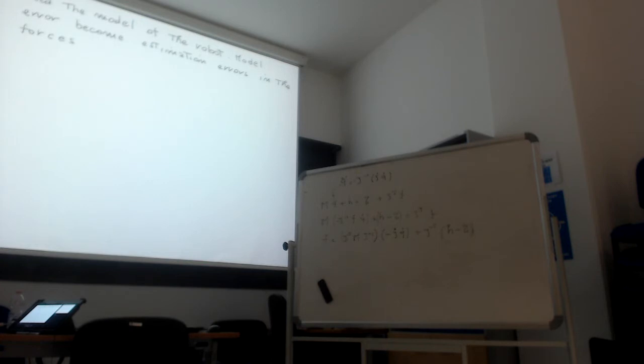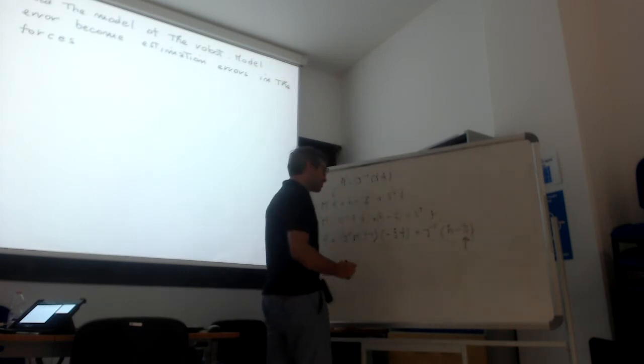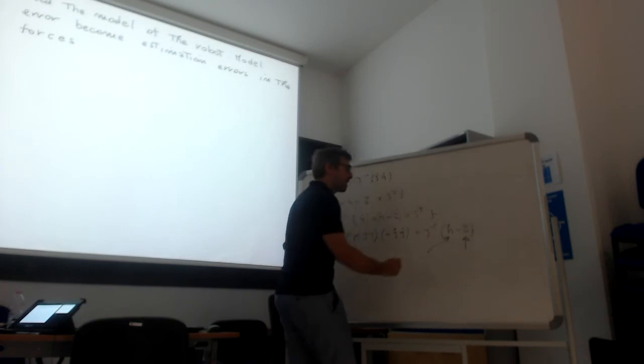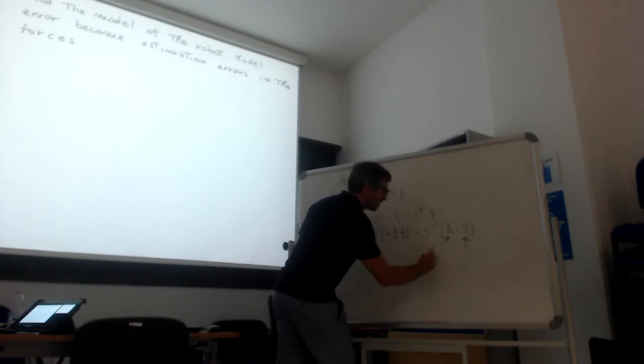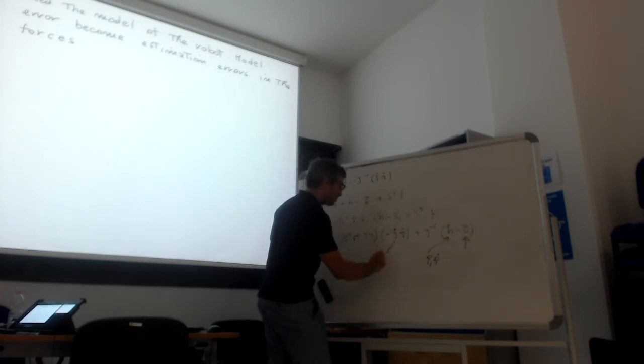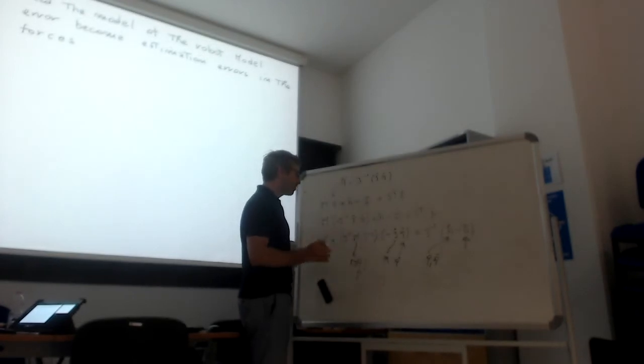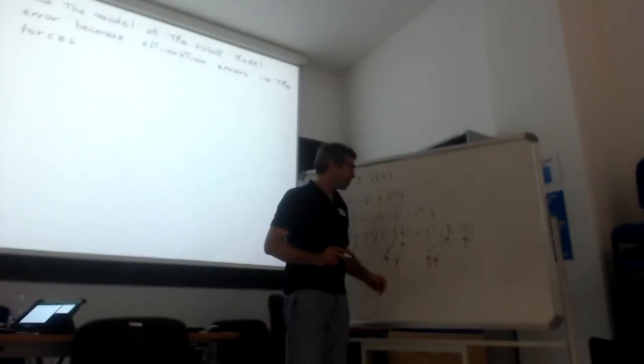The problem of this approach, it's cool because we measure the torque in essence from our sensor. We have torque sensors. We compute the bias because we have the encoders, so we can get position and velocity. Again, we can compute the Jacobian derivative because we have position of the joints. We have a velocity here measured. The mass matrix is joint dependent, so we have the position of the joint, Jacobian again. We know everything, measuring actually position, velocity, and torques.